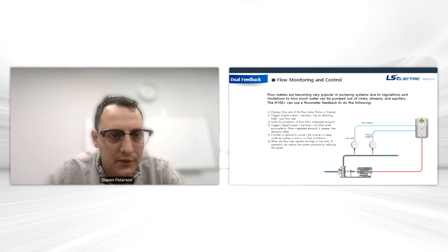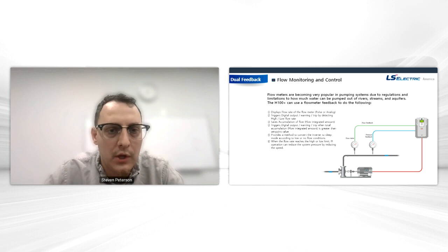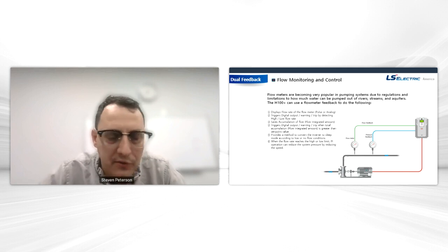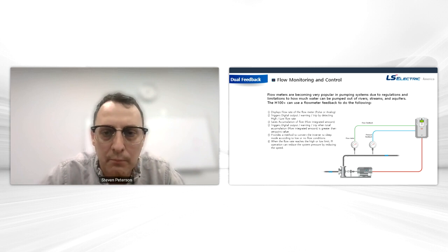I think we're coming on the last few functions here, with one of them being flow monitoring and control. So we could control the drive based on flow. It seems like more people are just monitoring flow. With a lot of these larger pumping systems, I get a lot of calls from people out west with big horsepower just pumping off of rivers and such. A lot of times there's regulations and limitations on how much water you could pump out of a reservoir on a given day and a given time.